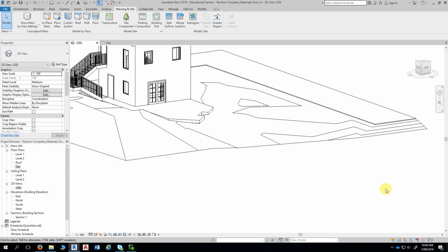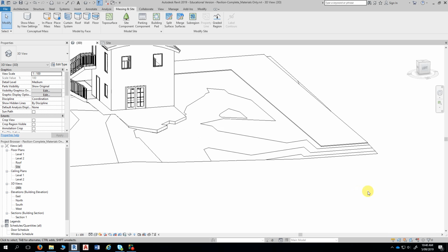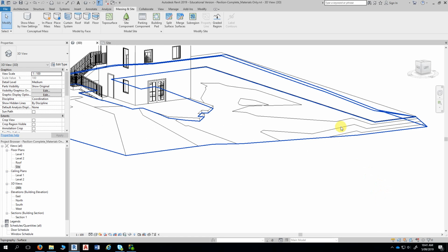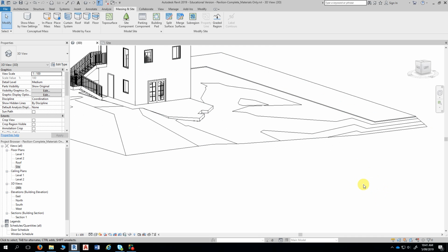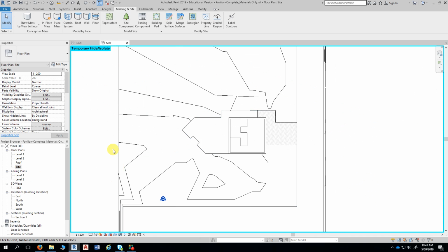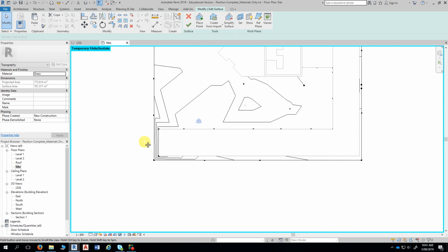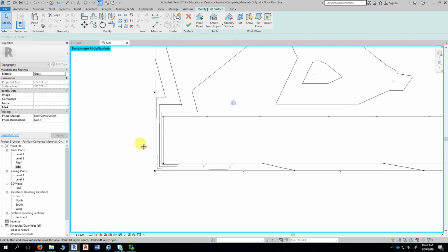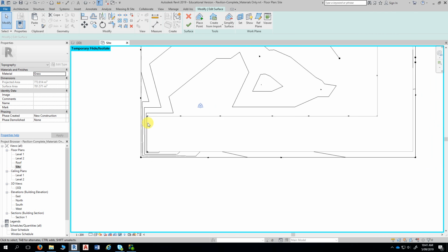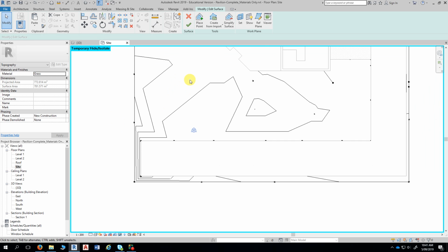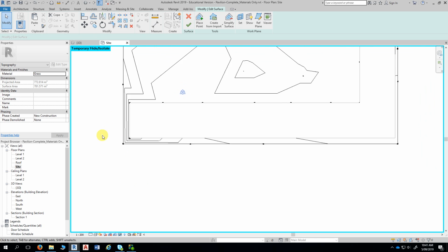Yes, question? I'm just drawing a triangle from one corner to the other, and it looks like it's that whole region. Yeah, if you're getting a result that you didn't expect, it might be advisable to go back and re-edit the surface and have a look at where you put your points. You might have inadvertently put a point out somewhere out here, perhaps, so just check your points.